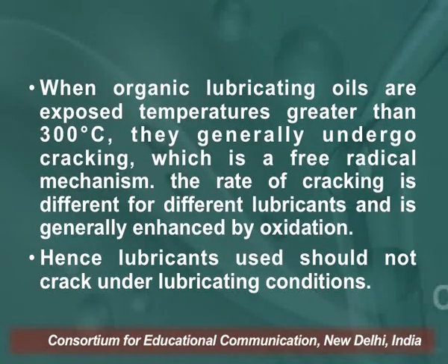When organic lubricating oils are exposed to temperatures greater than 300 degrees centigrade, they generally undergo cracking, which is a free radical mechanism. The rate of cracking is different for different lubricants and is generally enhanced by oxidation. Hence, lubricants used should also not crack under lubricating conditions.